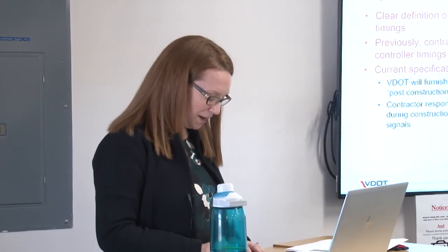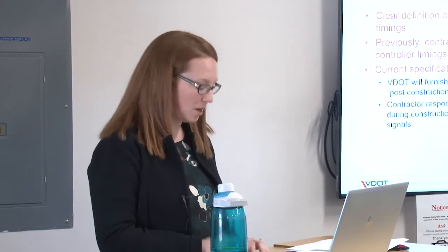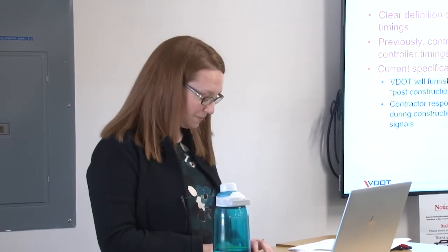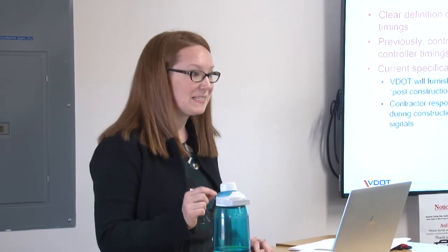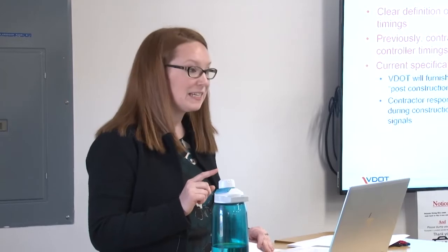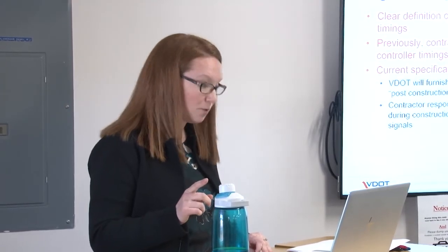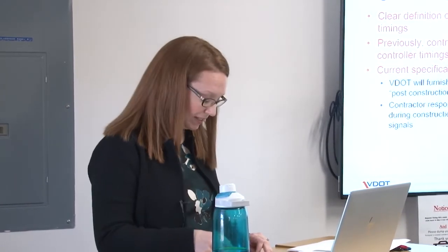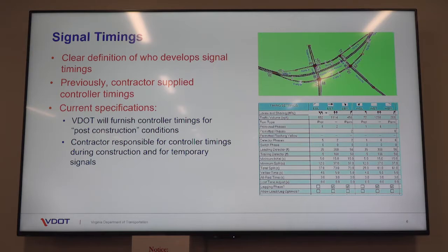Great. And then just something else to note on the traffic signal timings is that the clearance intervals need to be signed and sealed per TE 306.1 for both permanent and temporary signals. And again, who provides that may vary by district.